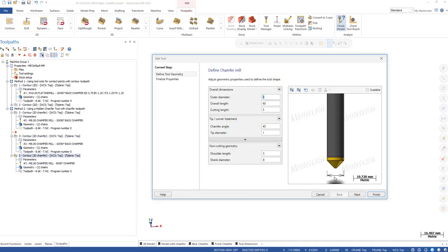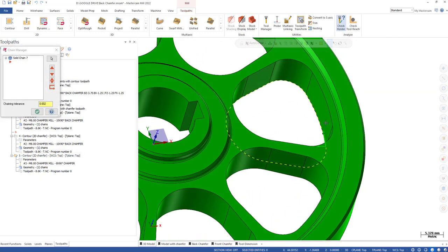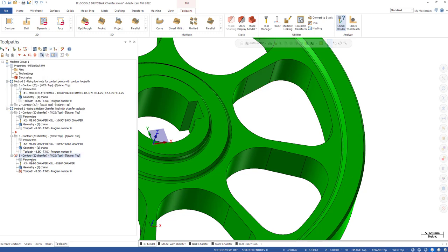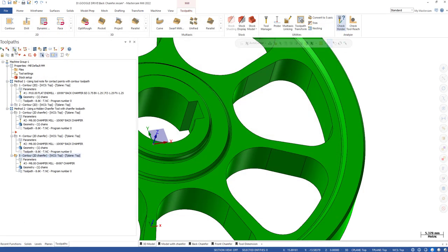First, I'm going to use a normal chamfer tool so you can see what happened. For example, I want to do the chamfer here on the bottom edge of the part. I go to the toolpath diameter, and instead of using the bottom offset, I select the top offset. So if top offset equals 0, this point of the chamfer will move to the top of the edge. So that's what we want.